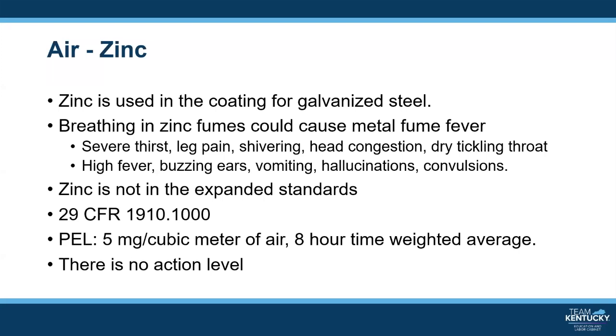Ways to protect yourself when welding on galvanized metal. In all operations where metal fume is present, you should work in a well-ventilated area. The best way to protect yourself against metal fumes is to use local exhaust ventilation at the source of the smoke. Do not recirculate the air within the shop.